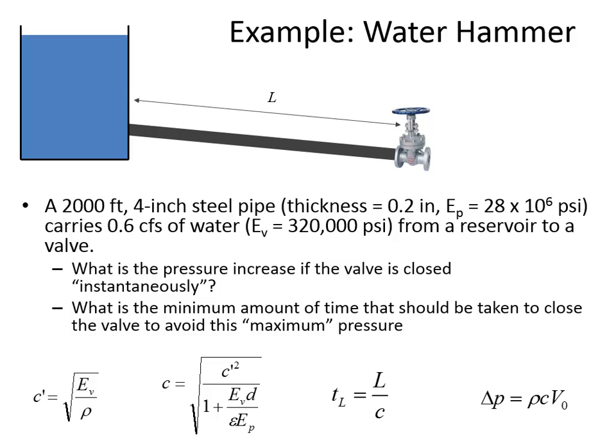That's about 2,800 kPa. The maximum allowable pressure on most water heaters is in the range of about 900 kPa. And so if a shock wave that big came through the system, it would cause most people's water heaters to fail. The water heater is usually the appliance in people's homes that fails the quickest.